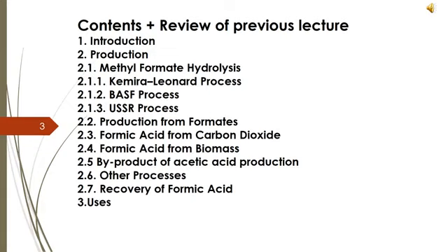Now from reactor D, what happened? The contact time was increased, equilibrium was established, then the reactor discharge, like formic acid which has been formed, and along with that, if reactants are there, they are flashed into the flash tank, that is E. Methyl formate, methanol and small quantities of formic acid were evaporated in the process and recycled to main reactor D. That is what I was saying: the methyl formate collected from B has been fed into C, the preliminary reactor, then into D, along with some recycled materials.